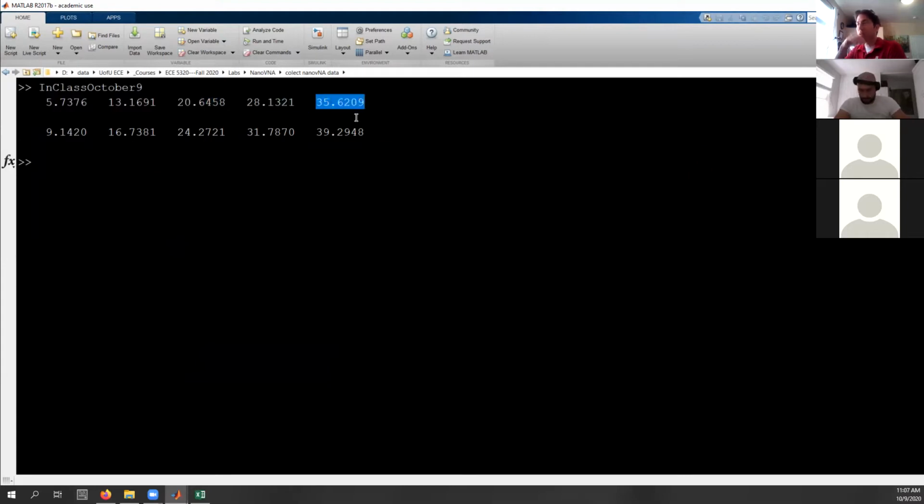So obviously, as you go higher in the mode number, you get higher cutoff frequencies associated with that mode. And it also tells us this mode here is our lowest cutoff. If I remember correctly, with the TE polarization, I think one of the other ones was the actual lower frequency. Does that sound right? So it looks like the 1-0 mode is in fact the fundamental mode of the entire waveguide.